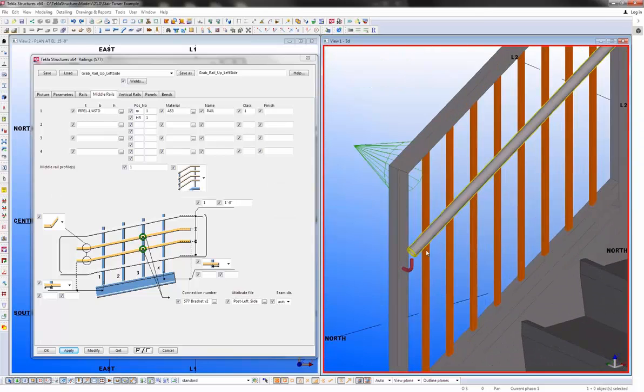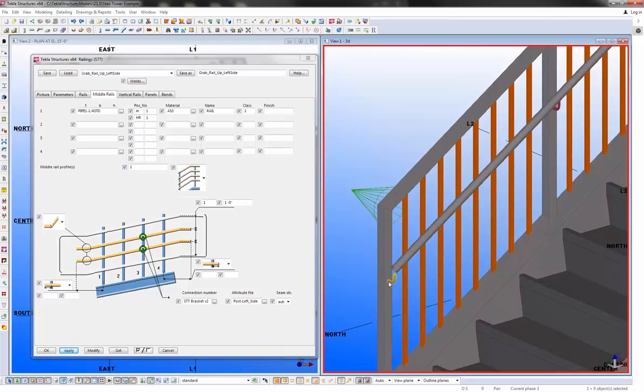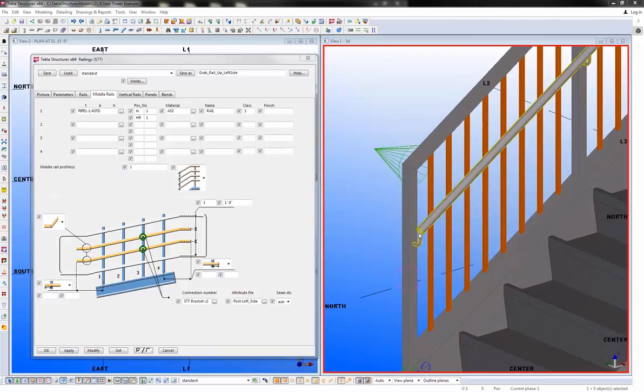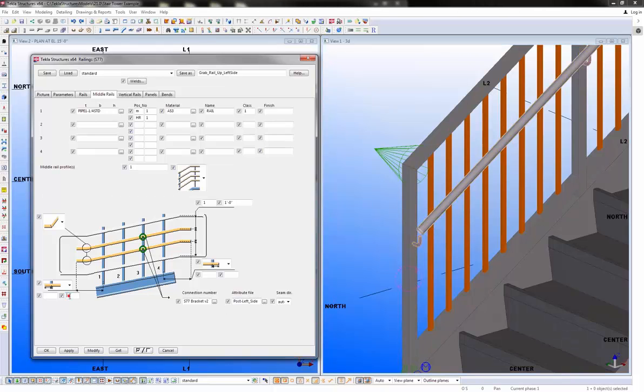So here we can see that it creates the rail, it creates some simple brackets, and I also have some options about how far it extends down past this bottom post. If I wanted, I could come in here and say that I wanted to extend maybe 6 inches, or maybe even a foot, and it will adjust that rail accordingly. I do want to show you though how you can make some of these bends and finishing parts custom using some manual tools like Polybeam.